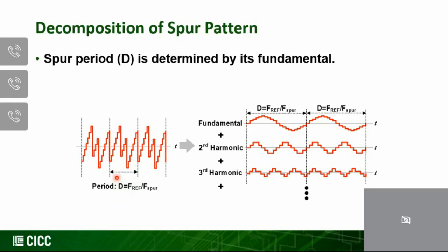Okay, so if we look at the Fourier transform of these noise patterns, we will see the fundamental frequency of this pattern, and the second harmonic of this pattern, and the third harmonic of this pattern. So let's first look at the fundamental frequency of this pattern. Sure enough, we are going to see some kind of disturbance at the frequency of this capital D, which is the fundamental frequency of this repeating noise pattern. And we are also going to see the second harmonic of this noise pattern.